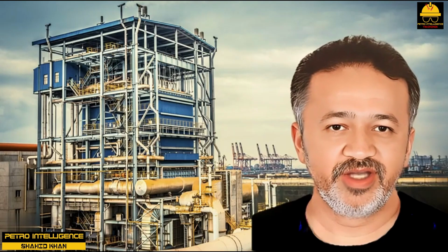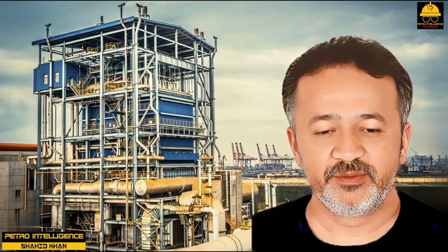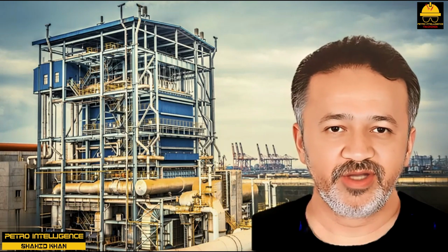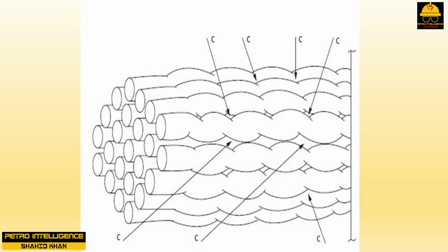Tube vibration in traditionally designed shell and tube exchangers, particularly at the point where the tubes pass through the tube support baffles, can cause the tubes to fail and leak. The other basic concept that is essential to the functioning of a tube bundle made with these twisted tubes is